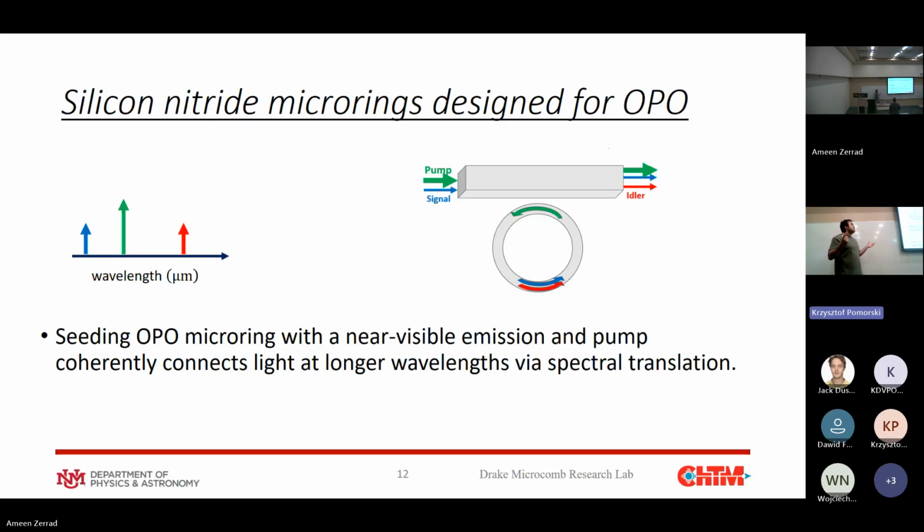The idea really is to design the bus waveguide in such a way that it minimizes propagation loss. So you don't want to lose that much light before you get to the resonator, because if you lost all that light, you might as well not have done it at all. And the coupling gap becomes very important for efficient outcoupling, which is another part of my talk later.